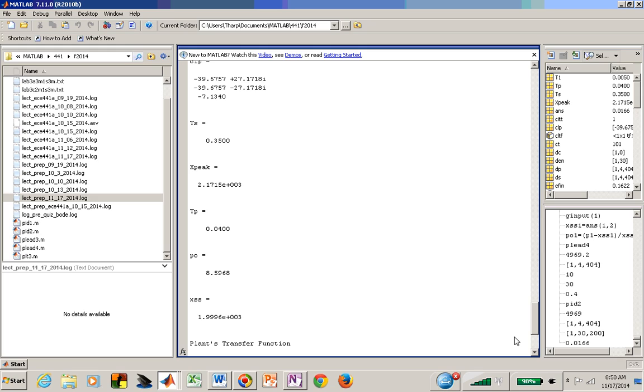Wednesday, what we're going to do is figure out how we sprinkle poles and zeros in the complex s-plane if somebody gives us an unstable system. We've looked at phase lead. We've looked a little bit at phase lag with a PI. We've now done PID, which is another way of thinking of a lead lag controller. It's giving you both steady state accuracy and transient behavior all in one. We'll pick up with stabilizing unstable systems on Wednesday.